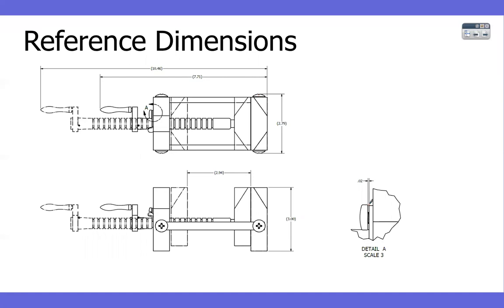But things like this, where this screw needs to be backed out that much, that is something that is going to be inspected. We're going to Loctite that screw, put it in, back it out that much, so that it leaves a little play. But that's going to get inspected. Make sure that it's right. Okay? Questions? So what does parentheses mean? Overall length. No, this one is an overall, but what does the parentheses mean? Reference, which means what? Not going to be checked. Don't check it. It's just there for information.